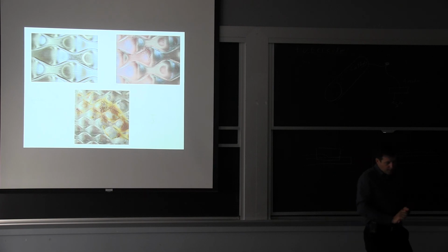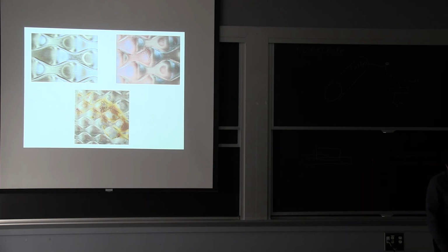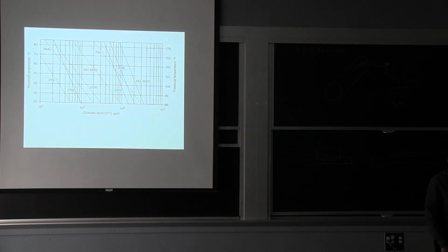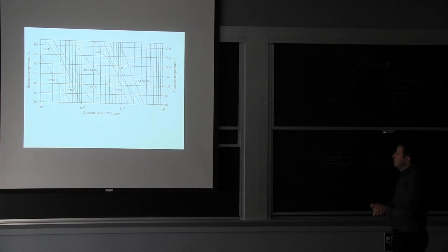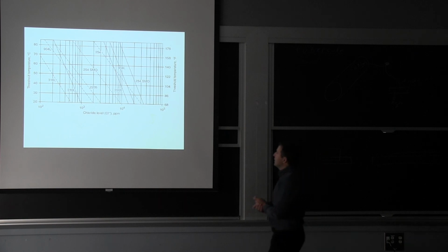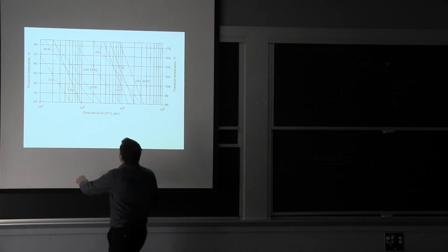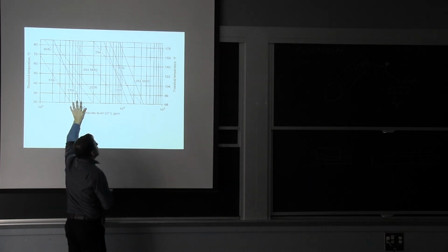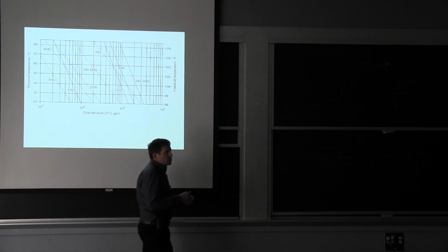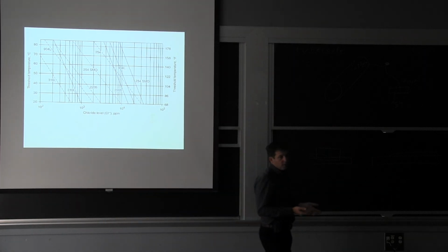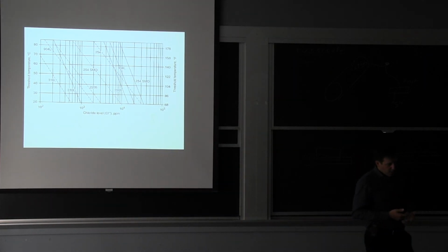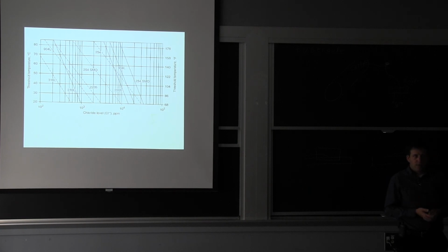So maybe the lesson with the stainless steel is they are not all with the same resistance to corrosion. Here you have different styles. I said what you were looking at was a 316, which is a good grade for just general use against corrosion. But if you're talking about an industrial application where you're going to have a lot of chlorides, then there are many more steps that you can go in the ability to resist the corrosion.